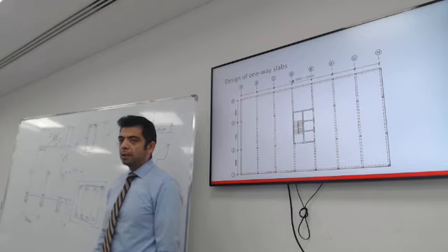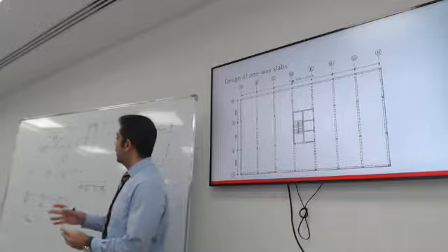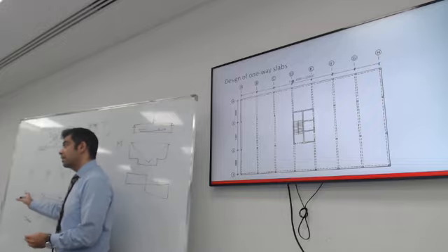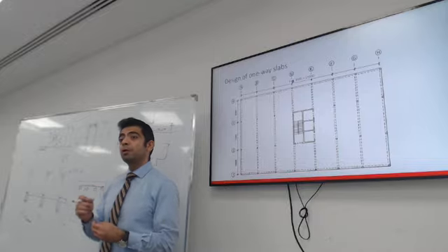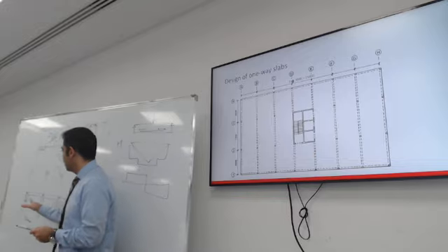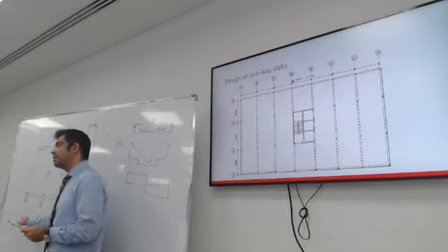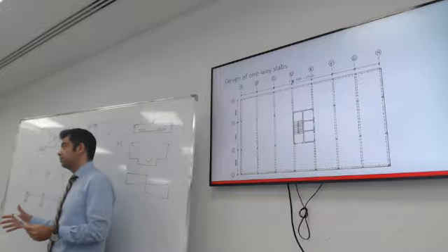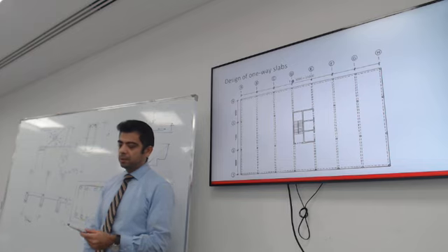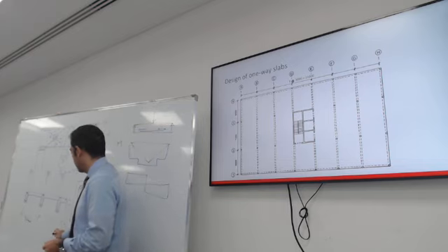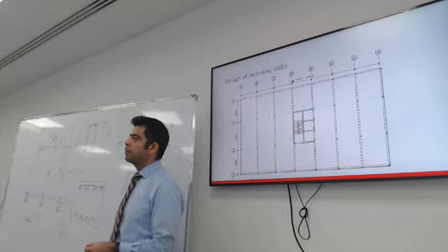You start with an assumption, a guideline, depending on the system. Is it a one-way slab, or is it a beam, or is it a two-way slab? It's a ratio of the span. For a simple beam, you start with a depth relative to the span divided by 10. This is a simple beam. You can divide by a bigger number for one-way slabs. All right? So let's say the thickness is going to be reasonable with 150.